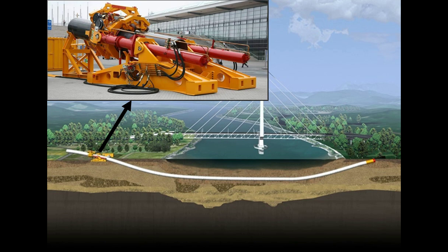This allows for prefabrication of relatively long pipe string or strings, depending on available workspace behind entry, so behind the pipe thruster. In front of the pipe thruster, the ground is excavated essentially as a curved microtunnel. It is a continuously cased, relatively low annular pressure, one-pass system, assuming no problems occur during construction that require pullback.